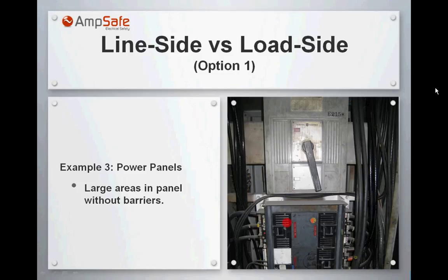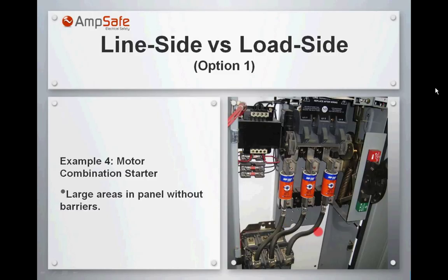Motor combination starters, again, have the line side and the load side. Which one are you going to use? Normally this is much higher than this, and there are no barriers to protect you if you're working with lower PPE on the load side when you have an arc flash incident on the line side.